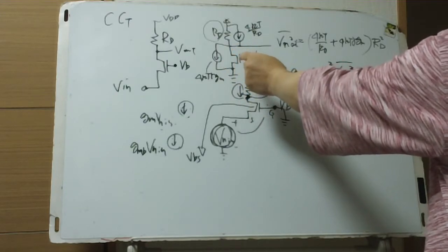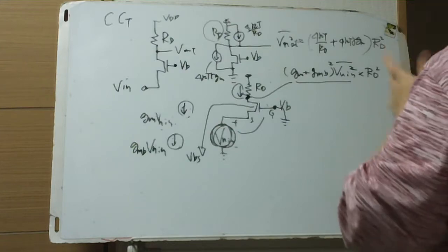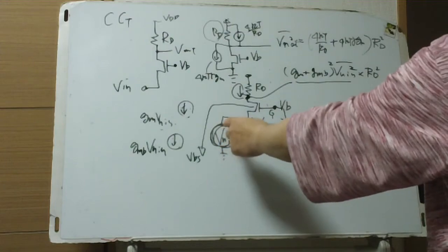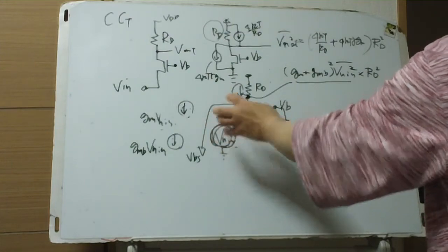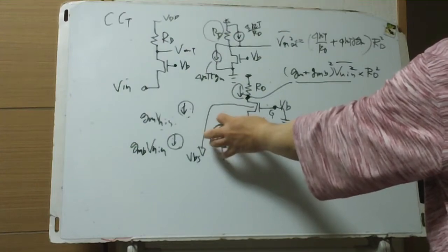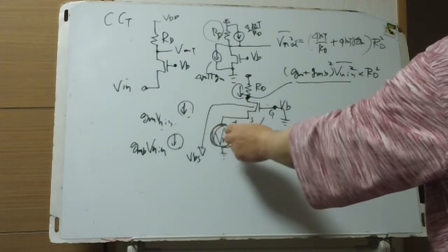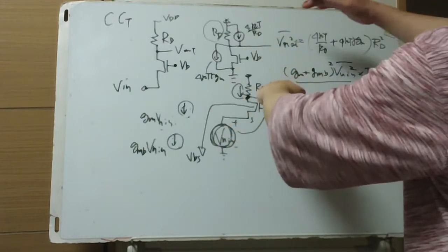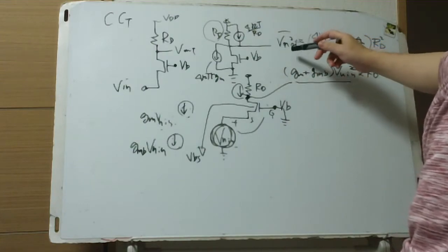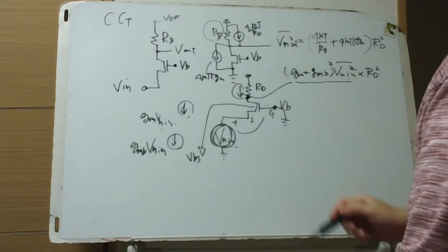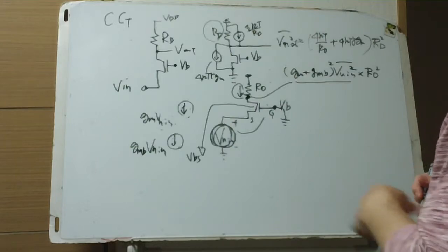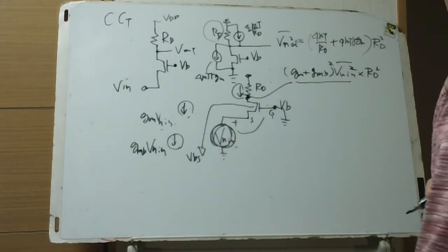This voltage, when making the input shorted, we can concentrate on the input noise voltage. If this is the input referred voltage noise, the output noise produced by this noise is comparable to this output noise. It's the same. We ran this procedure already from this book.